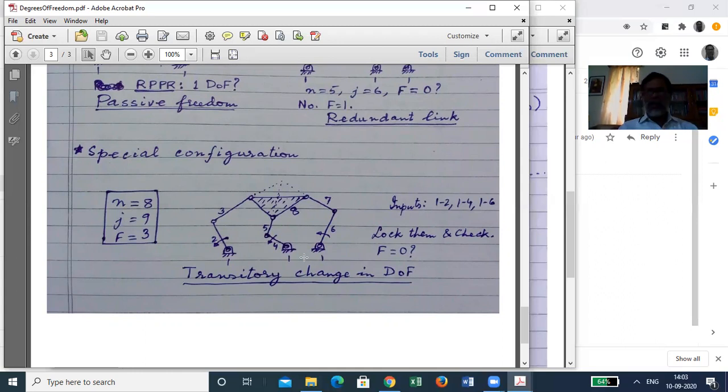And it has, at most of the configurations, 3 degrees of freedom, and that is why you give the 3 inputs at links 2, 4, and 6, relative to the frame, because they are closer to the frame and you have ease of mounting the motors. But you could have given the inputs to some other pairs. That is, you could have mounted the motors somewhere else.